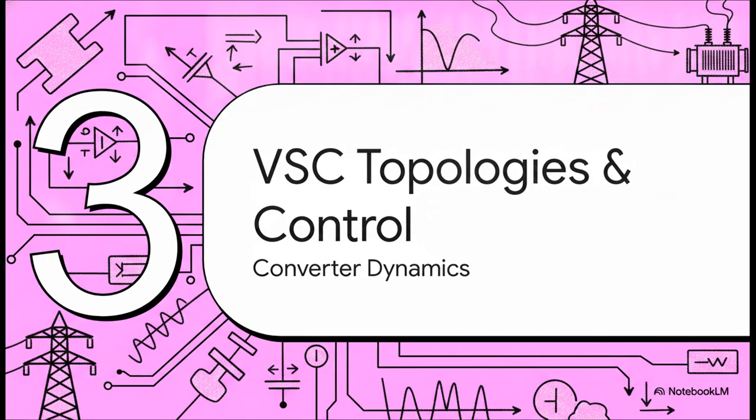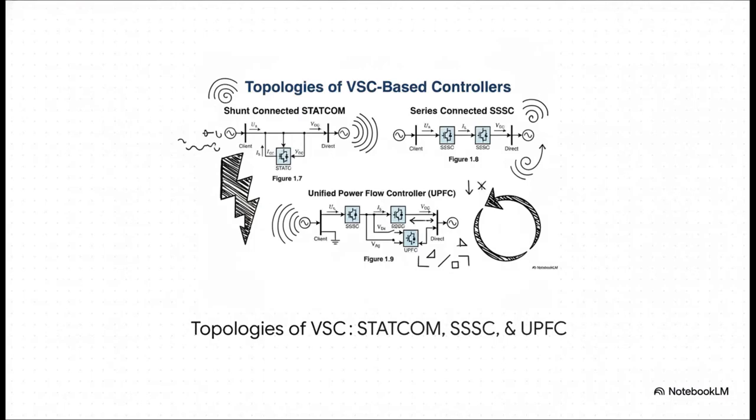The crucial point now is understanding the internal mechanics of these voltage source converters. We are going to deconstruct them circuit by circuit. Announcing Slide 8, let's verbally trace every block, signal, and connection for these three figures. Figure 1.7 is the STATCOM topology. Acting in a shunt or parallel connection, it draws DC voltage to inject shunt current.